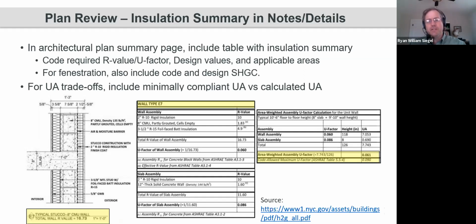And so again, considering the construction order and constructability, putting continuous insulation on the exterior of a building may be easier, even if it's a little bit more expensive of a product than the bat product. Here, just an extra inch of insulation on the exterior would avoid the entire process of insulating the cavities on the inside.